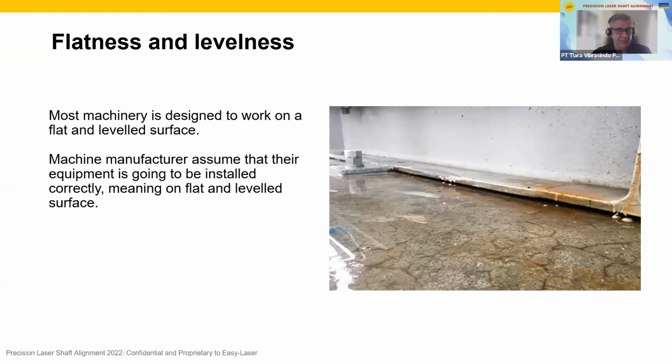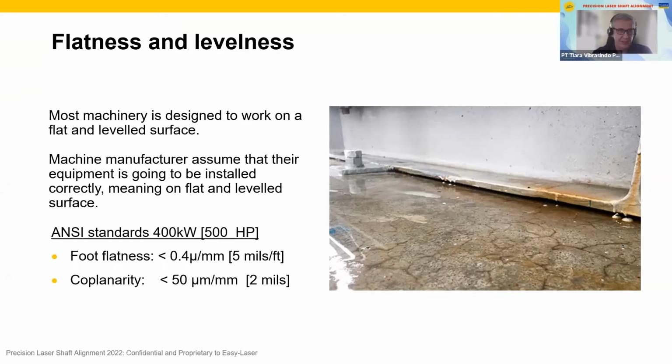So there are standards for the installation as well. There is the ANSI standard, which recommends foot flatness. So ANSI, American National Standards Institute, for example, says foot flatness should be less than 0.4 micron per millimeter.